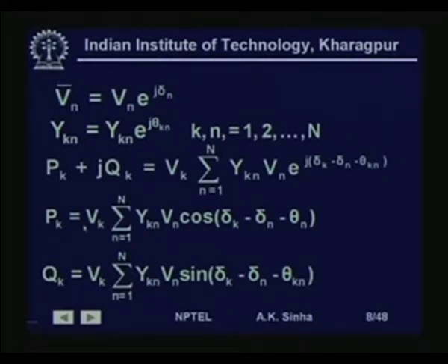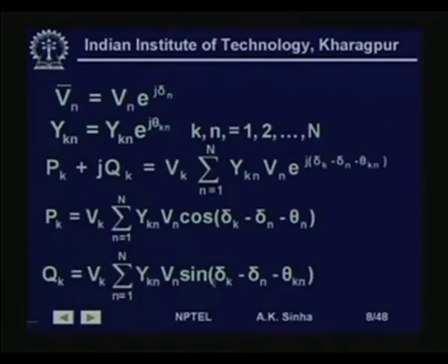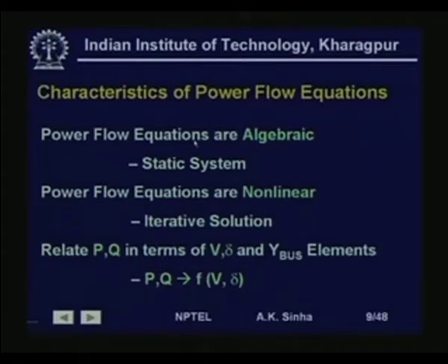k. Now, let us see the characteristics of the power flow equation. Now, power flow equations, as we see from here, are algebraic equations, since they are not a function of time. So, these equations represent a static system. We have already said earlier that power flow equations basically provide a snapshot value for the voltage and power flows at various buses. So, this is a static system analysis that we are doing.